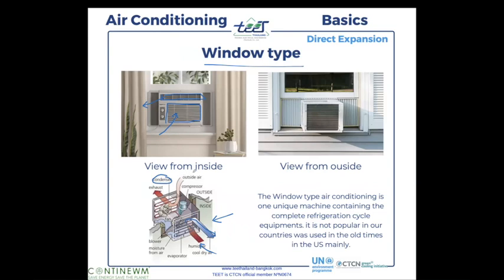So it takes the outside air from the top here. You can see, from the outside view on the right side, this grid here. So here you have the air that is warm, but colder than the compressed gas, okay? That is getting inside, and that is blown with a fan outside through the condenser, okay?